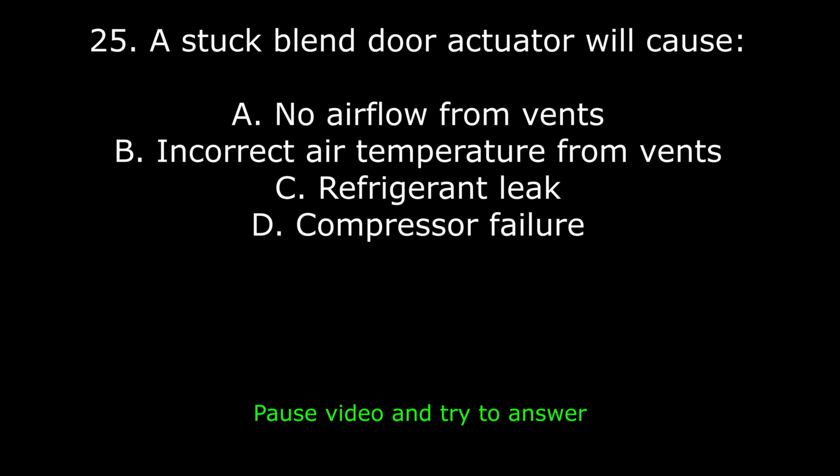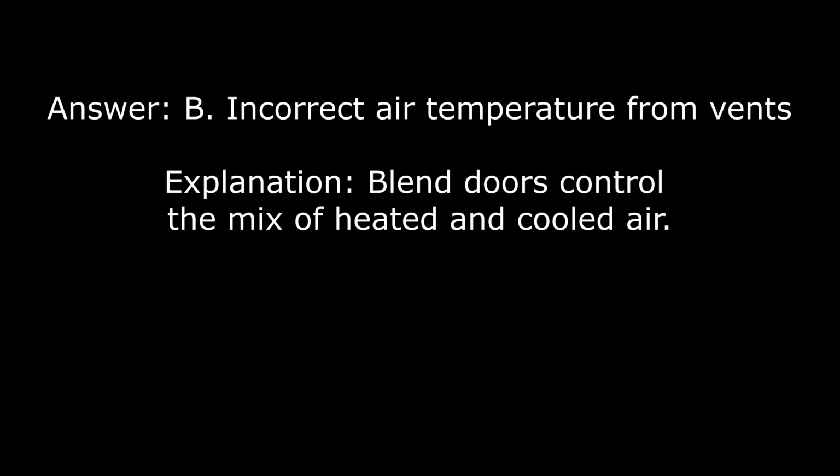25. A stuck blend door actuator will cause A. No airflow from vents. B. Incorrect air temperature from vents. C. Refrigerant leak. D. Compressor failure. Answer: B. Incorrect air temperature from vents. Explanation: blend doors control the mix of heated and cooled air.